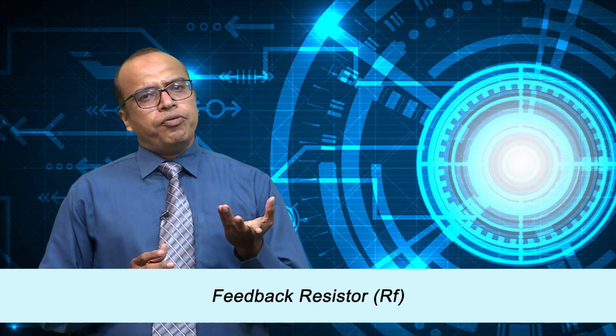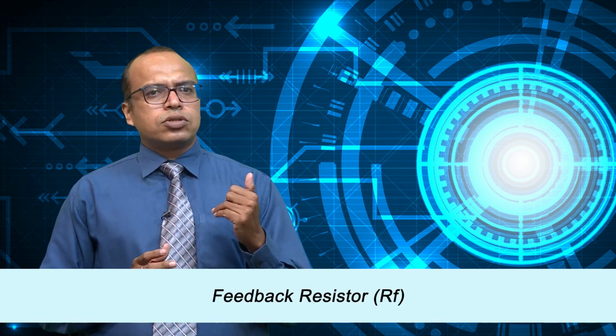Once again, the feedback resistor. We discuss this resistor repeatedly, but you have to know the importance of negative feedback. RF plays a crucial role in determining the scaling factor of the output voltage. By changing the value of RF, you can adjust the gain of the circuit.